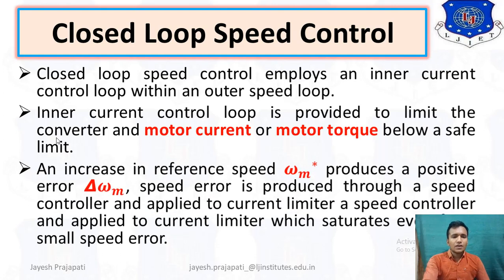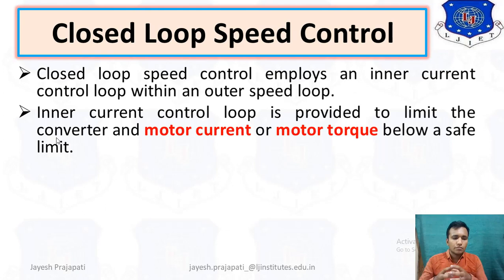In some schemes the current is controlled directly, but in other schemes it is controlled indirectly. For example, in a variable frequency induction motor drive, the current is controlled by the slip, because we know that the speed ns is proportional to this slip also. Slip is ns minus n divided by ns. So we have to control the variable frequency of this motor by the slip. Sometimes we control directly, but sometimes indirectly also. So at that time we have to take this type of control loop system.